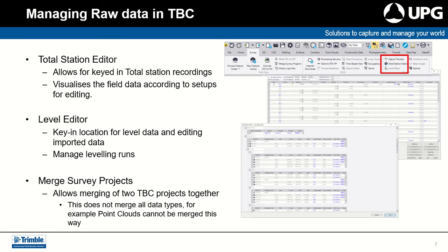When you're looking at the optical grouping, there are two main buttons here that I would look at. One is the total station editor, where you will see the information that we've stored in the points and the optical spreadsheets that we talked about previously. However, we're showing you the information based on the total station setup. So you will see the total station setup, and then associated with that will be all the points that are taken at that particular total station. We categorize the points in terms of whether it's part of the traverse or whether they were a physical check shot as well, so it may be easier to view and review your data in the total station editor than it is in an optical or point spreadsheet.